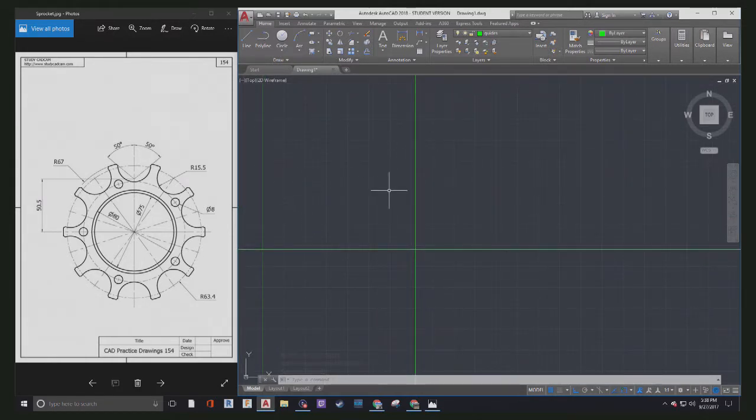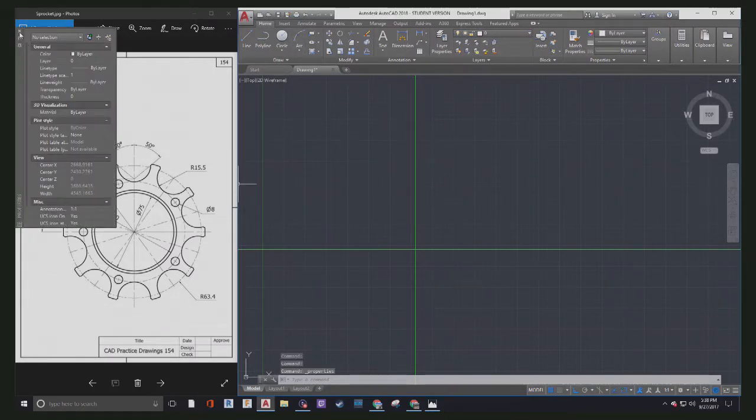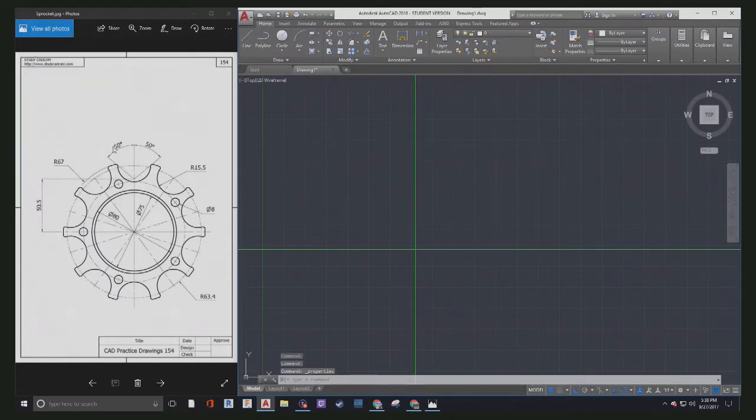Now that we have our crosshairs here, I'm going to create my circles here. So I'm going to go to my normal layer here, and notice that these are diameters that I see over on the left. So if we take a look on the left here, we can see that I have an outer diameter of 80 and an inner diameter of 75.